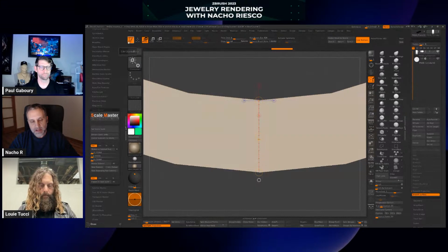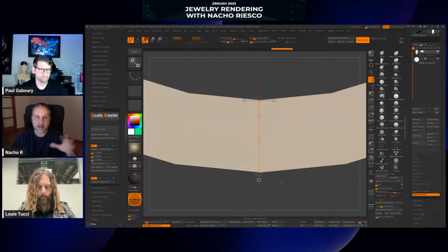If the customer has given us an average of 2 millimeters, depending on the kind of metals, even if we are just designing the piece, that means that during the designing process we are going to change our mind. In some cases it's going to be necessary to make it thicker, and in some cases thinner. So when we are creating jewelry, one of the main rules is to know that we are going to have enough metal to lose during the casting or during the polishing process.